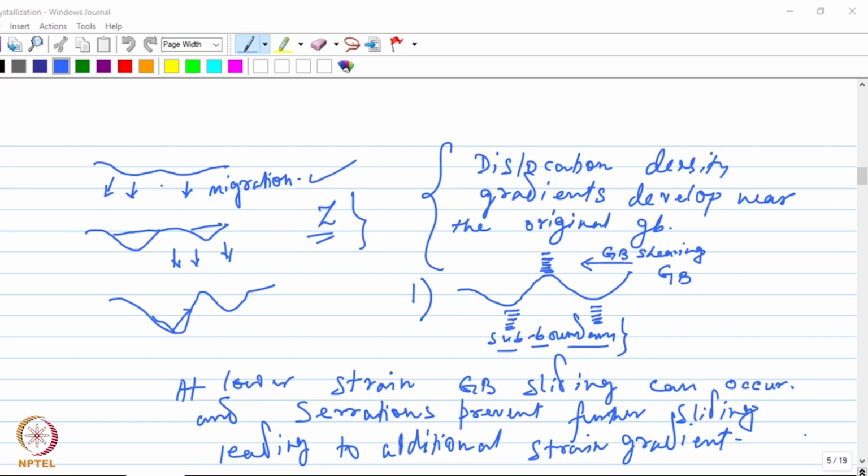Low stacking fault energy means less cross slip, and as a result the dislocations will not move much and will accumulate, giving rise to a high dislocation density in certain regions of the crystal that will lead to a strain energy gradient across the grain boundaries, which will ultimately drive the nucleation process.